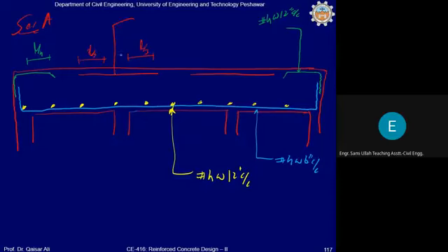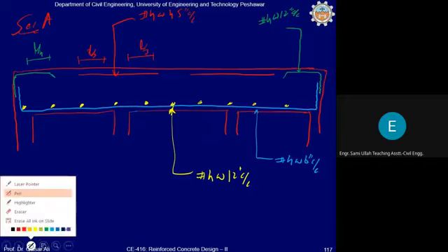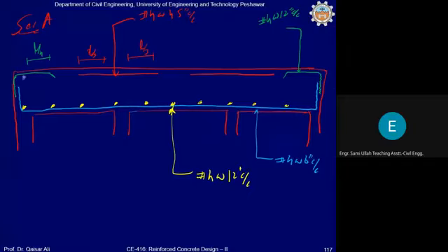And the spacing is number 4 at 4.5 inch. Okay. And of course, the supporting bars normally go at 18 inch center to center. These are the supporting bars. So the spacing of supporting bar is number 4 at 18 inch. Correct?